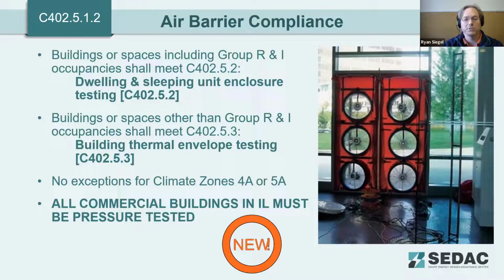And so the importance of actually testing and verifying that the air barrier is complete and performing adequately. So this is also maybe known as envelope commissioning. We've commissioned HVAC systems and lighting systems, and understanding that envelopes have become more and more complex systems, they also need to be commissioned as well.